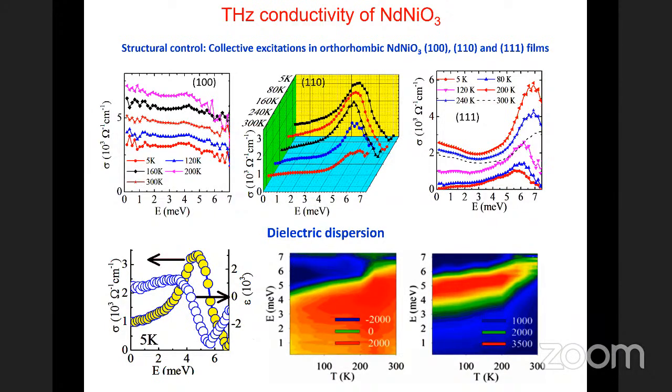And in this system, we took the template substrate in 3 different major directions, 100, 110, and 111 oriented substrates. And we deposited these films on the substrates with different orthorhombic distortions. All the films on 110 and 111 were orthorhombically distorted, while on 100 they were tetragonal.